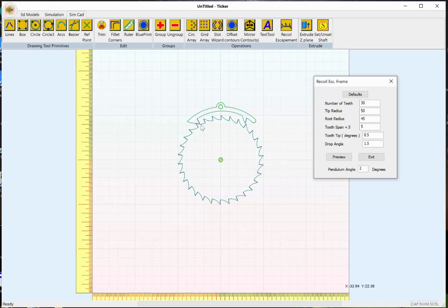Now, an escapement such as an anchor releases a half a tooth per beat. So if you have a 1-second beat and a 30-tooth wheel, you will get this ratchet turning once for every minute, and that allows you to use the center axle of this ratchet as a second hand. Now, if you're not designing a clock that you want a second hand, it wouldn't be unusual to use, for example, 36 teeth.